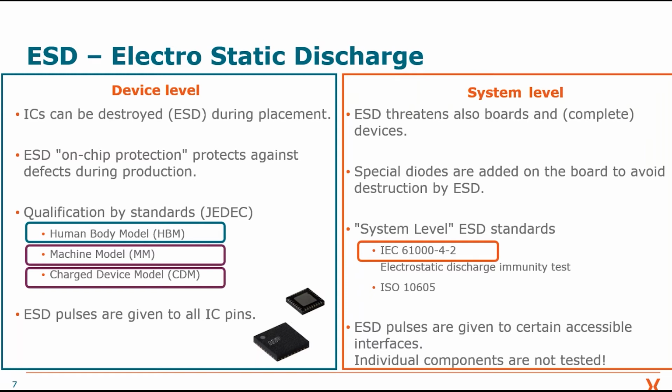So there is the question, if you're taking care of ESD, you want to be prepared for this. And in order to do so, you need to simulate this event, and it's usually done by compliance testing in EMC labs.